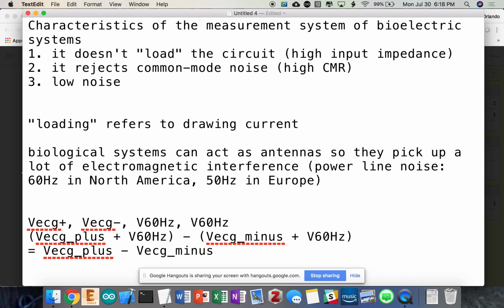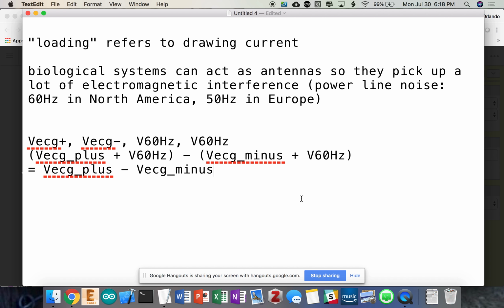So if you're just having two electrodes in, you don't really even have to account for the noise because it'll get subtracted out? Yep. Typically, though, you'll want to use three electrodes because your third electrode will be a reference. Although devices like chest strap heart rate monitors actually only use two electrodes because they create a virtual reference.